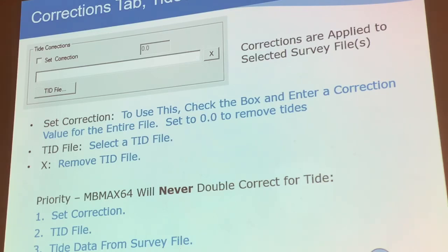If anything is not understood, you can ask. The correction of the tide, when shown in the command, is it minus or plus? It depends on which sign convention you use. It's always addition for this, but if you put plus, then you will minus from the data. But if you put minus, you will plus to the data.